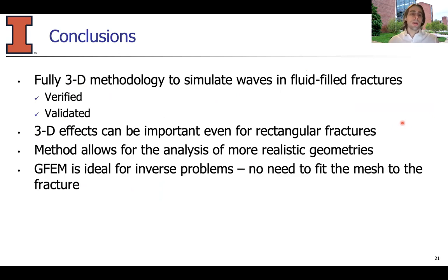And I would like to point out that the GFEM is ideal for inverse problems, because there's no need to fit the mesh to the fracture. So in inverse problems, where you want to try different fracture geometries to see the one that fits the field data, you don't need to create different meshes for the different fracture geometries with the GFEM.